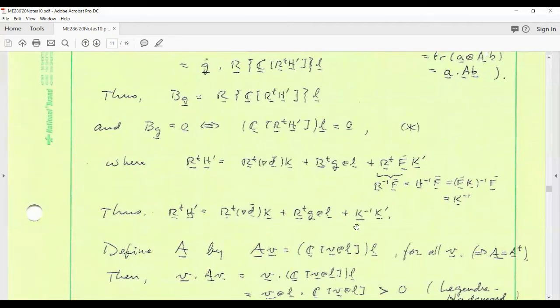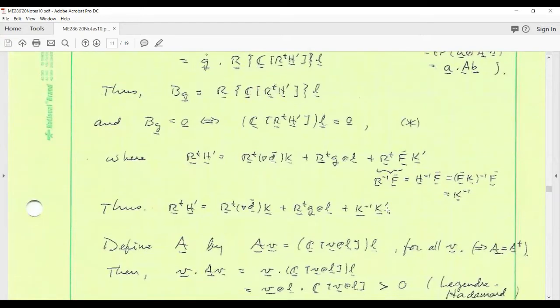So this is going to be an important term actually, because the through thickness derivative of K is what's going to induce the plate to bend due to plastic deformation. We'll see it momentarily. Okay, the rest is an algebraic problem then, how to solve this equation where R transpose H prime is this. And we see the G, the unknown, sits right here. That's the thing we're trying to solve for.